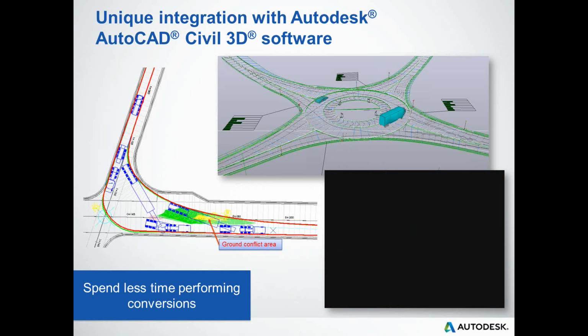As I mentioned, analysis or design results for the roundabouts. Again, you have design rules attached as the basis for your roundabout. What the software will do is calculate at what speed you can take, for instance, the roundabout going from the bottom right leg to the upper right leg. If that speed is beyond the acceptable speed, then you will get a red color indicating that this is not a safe situation.